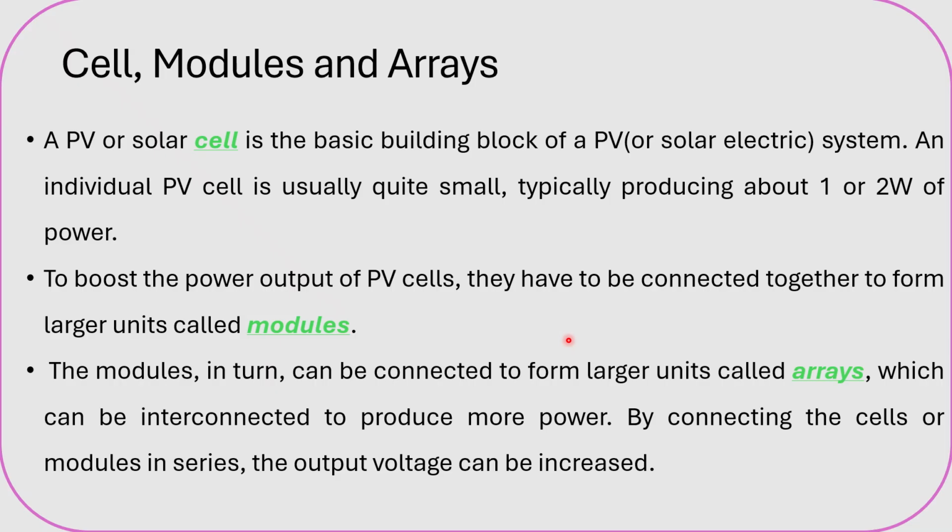Whereas concentrator systems collect a large amount of sunlight and focus it onto the target PV panels using lenses and reflectors. Unlike the flat panel, the concentrator has reflectors or lenses. These systems reduce the size and required number of cells, while the power output is increased. Moreover, by concentrating the solar light, the efficiency of the PV cell is also increased.